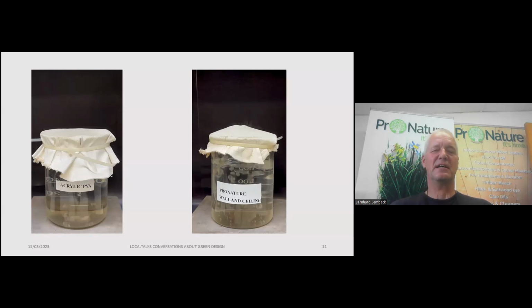And we strapped this cloth that had been curing for a number of days, so that we have a proper dry paint film, over a beaker on a hot plate and just boiled the water underneath, and wanted to see which coating is more permeable than the other. And if we have a look at the acrylic PVA, that was happily boiling and nothing really happened.